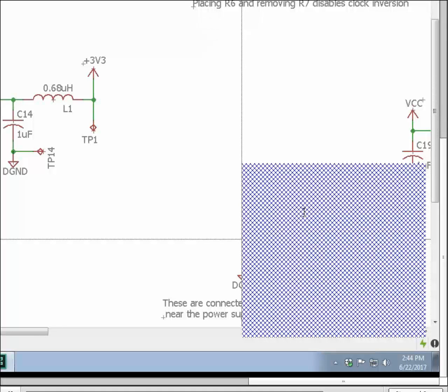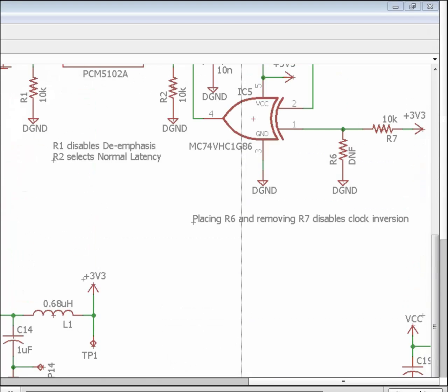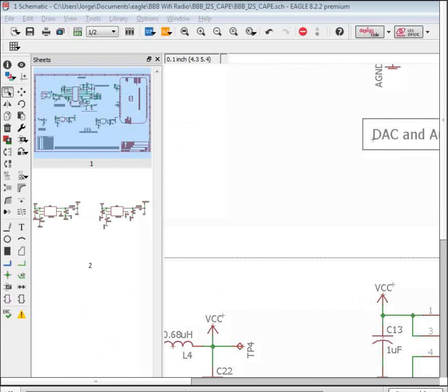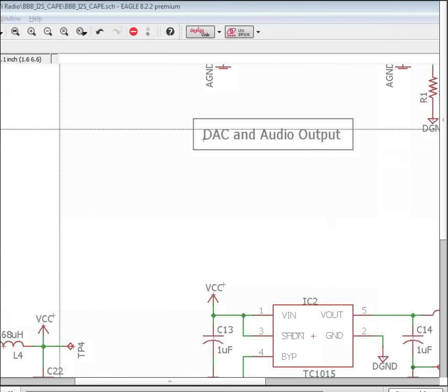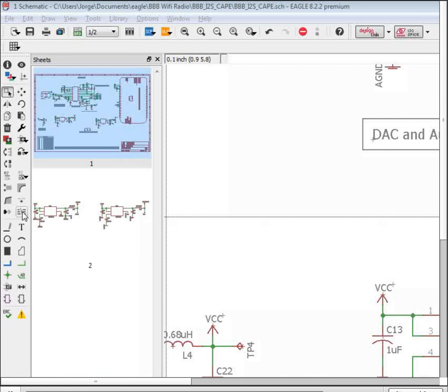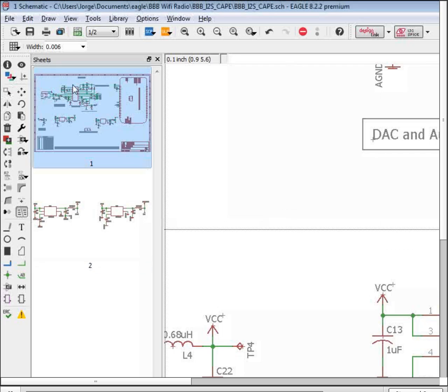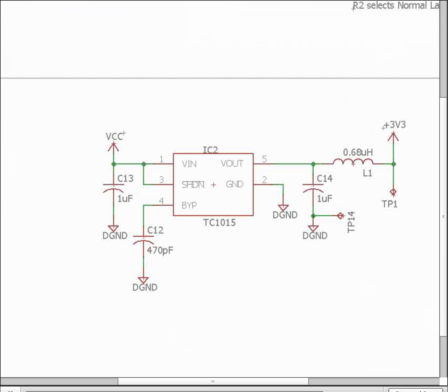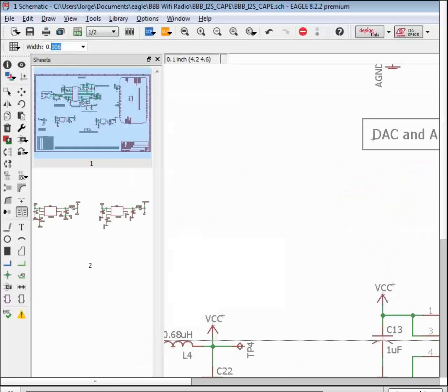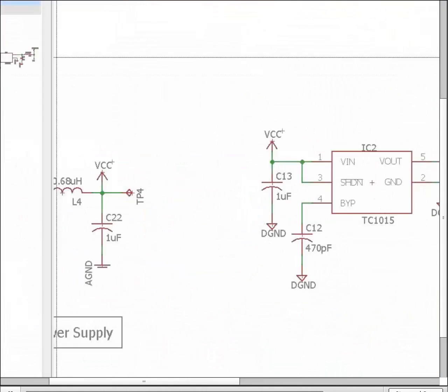The only thing you have to be careful of here is setting the separation. Thanks to the pin snap feature, it's not super critical to be on a 0.1 inch grid anymore, but it still is useful to do it. So in the case of the slice tool, if you're going to use it in a schematic, you would make sure to pick some multiple of 0.1. So you might use 0.1 itself. That way, wherever it cuts, you have half a grid distance on each side of it, and that would keep you on grid. So that's kind of the only thing to keep in mind with slice on the schematic.